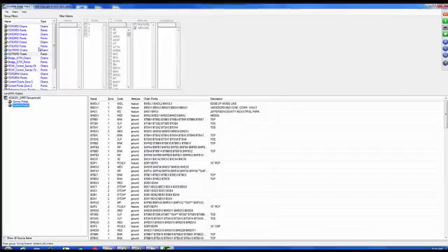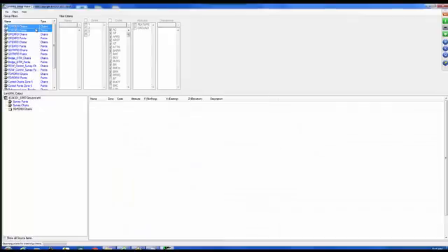So what we're going to do first here is go up to TopoRD Chains. We're going to hold the Shift key down, and we're going to pick a range from TopoRD down to TopoRD points. Okay, so we're going to build both of these groups in one shot. We're not going to make any changes to the filter criteria. We're going to right-click, and we're going to say Create the Group. So now, for the group called TopoRD Chains, we now have our chains. That looks valid, and we now have our points. All right? So you can see the process.